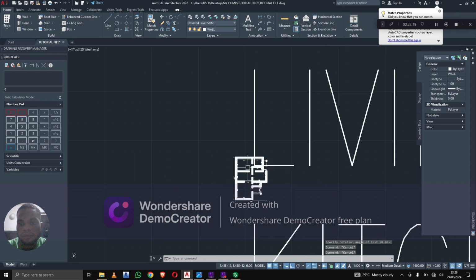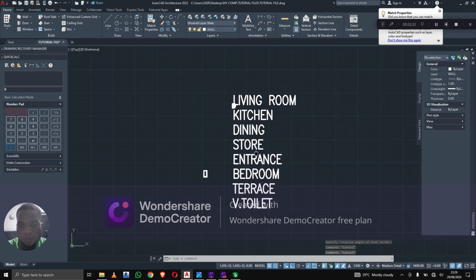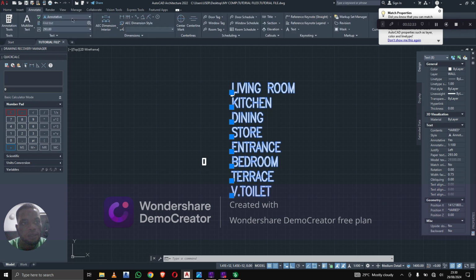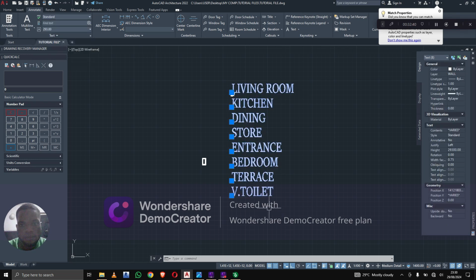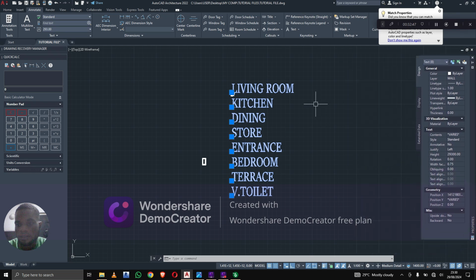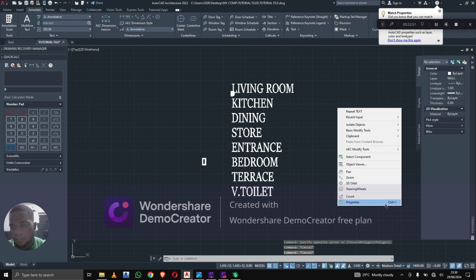Unfortunately, these things are very big. So let's change the height. Come to annotate here. You see annotate here. Click annotate. We have a very good font here. Let's manage this. So reduce the height by coming here. If you don't see this box outside, just right click and check properties. Click it. You see it has gone. Click on it and see it is back.